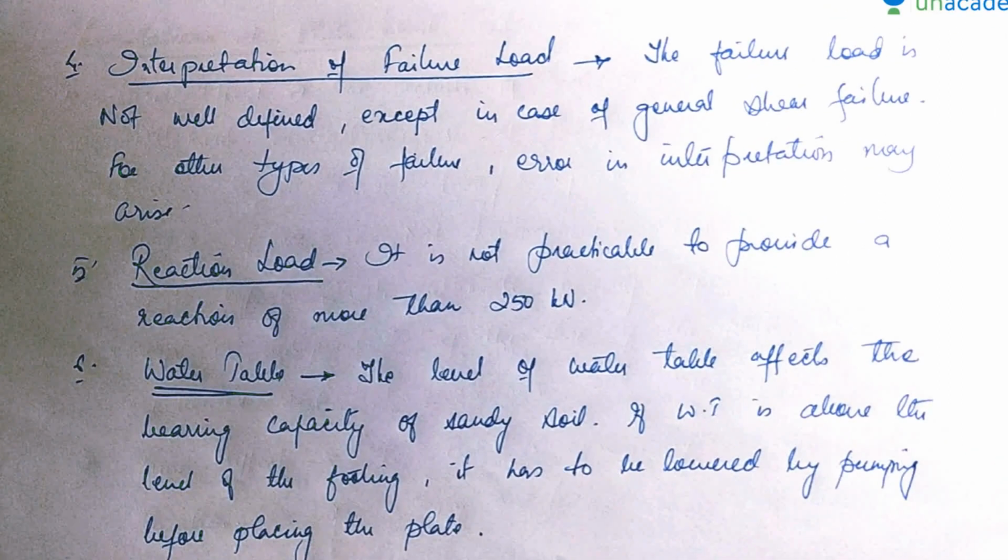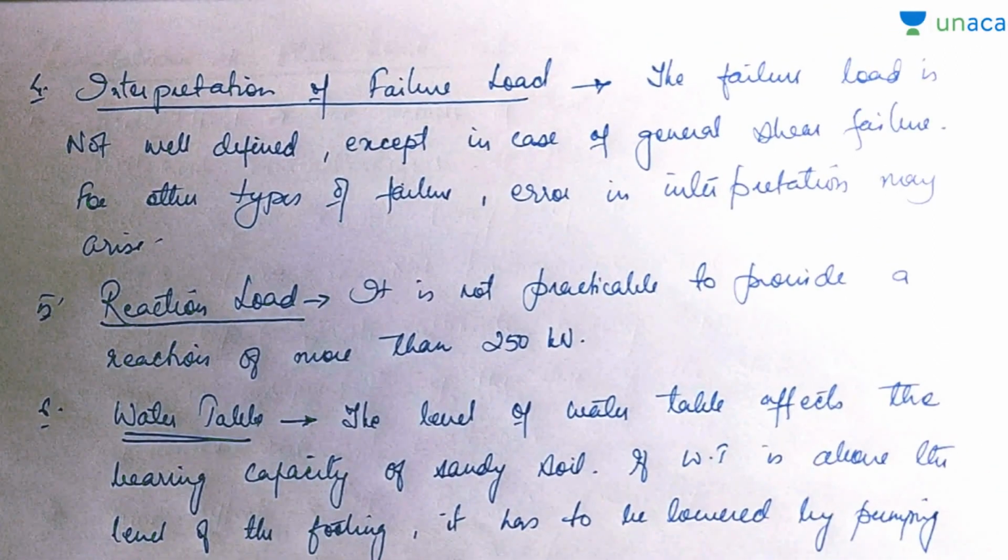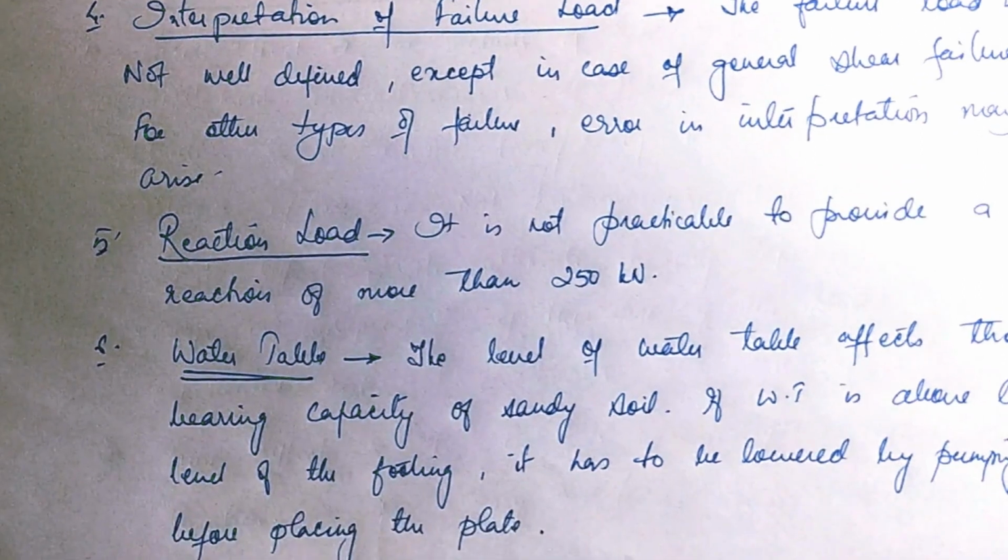Now, there is one more: interpretation of failure load. The failure load is not well defined except in case of general shear failure. And for other types of failure, the error is in the interpretation, so there are chances of error arising.